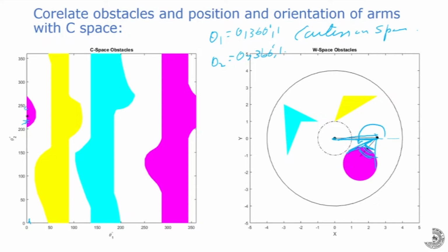Again we take one round, and when it takes one round, link 2 is going to hit this again. So from here to here it is hitting again, okay. Wherever it is hitting, I put a mark with that respective color. Then I move further, and we see that somewhere around here, equal to 25, link 2 will start hitting the yellow obstacle now, okay. It was hitting the orange and the pink one, but now it will start hitting the yellow one, okay. So it is somewhere here, okay.